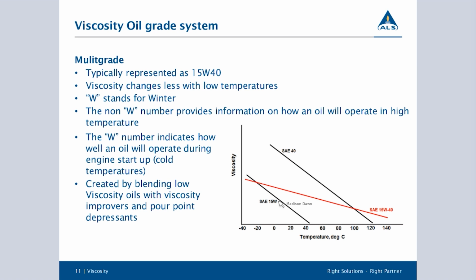The same thing over here with your SAE 15W. You can see that the SAE 15W works really well at cold temperatures, and the SAE 40 does a little better at higher temperatures, because you do want to be operating at maybe a lower viscosity, because up here we get very thick. And if you mix the two together, and I'm not actually telling you to take an SAE 15 and an SAE 10 and mix them together, but if you create an SAE 10W40, you start to see that graph changes, and that's what we see with this red line.